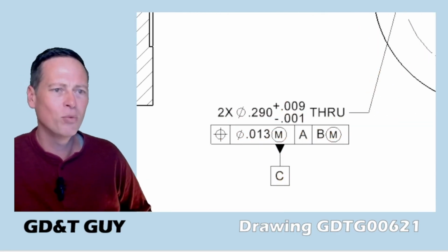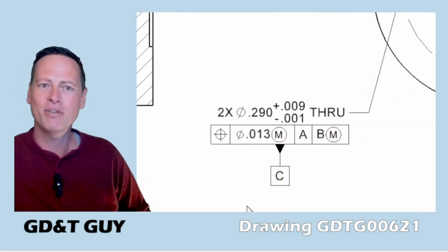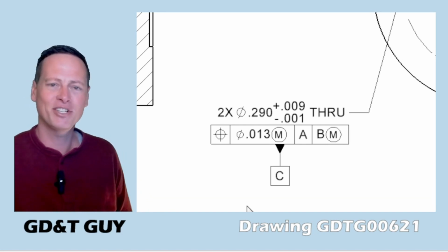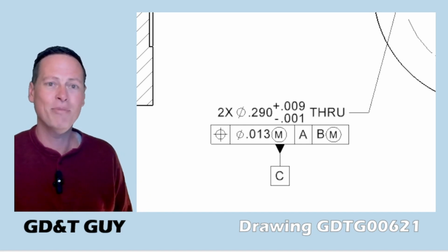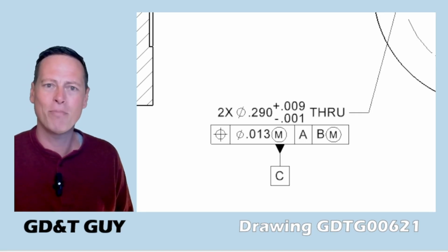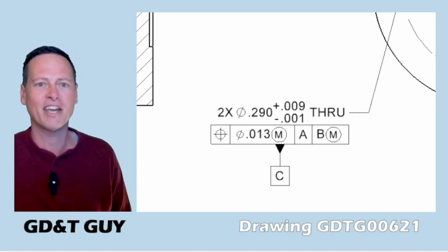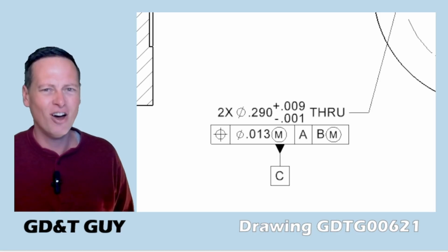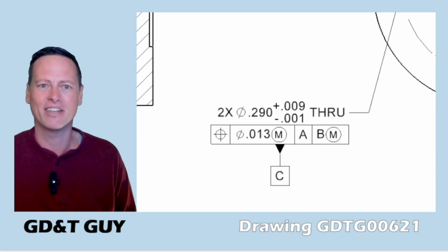Maybe we could go back to one callout and then use the pattern of two holes as a tertiary datum feature. And I'm not sure I've even seen very much of this. What you see more often is for a pattern of screw holes to be used as a secondary datum feature. Also pretty often a bad idea, I think, even though the standard seems to push it.